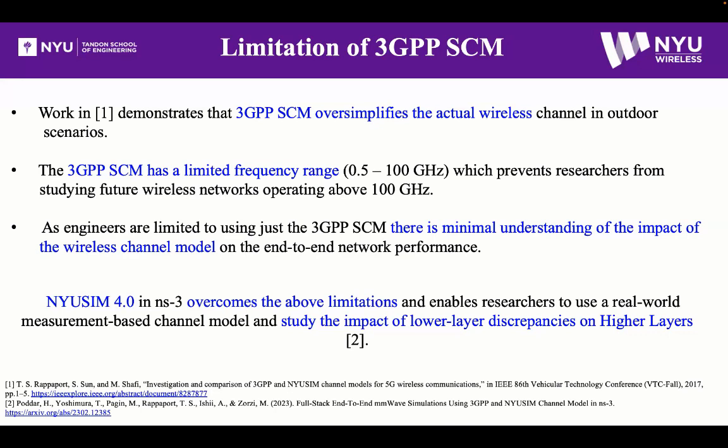For example, how your channel model impacts your SINRs, and how that translates to impacting your end-to-end throughputs and network performance. We implemented NYUSIM 4.0 in NS3, and under the hood, NYUSIM 4.0 in NS3 relies heavily upon the MATLAB implementation that we already have. So there are two different simulator components: one is MATLAB-based and the other is NS3-based.